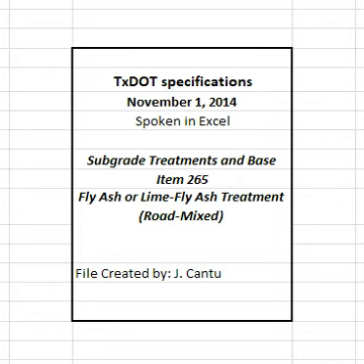4.7.2 FA treated sections with CS. Cure the finished section for at least 24 hours before opening to traffic unless otherwise directed. Curing may be accomplished by placing material to be used in the subsequent course instead of moist curing. Allow the treated course to dry for at least 48 hours before applying a prime coat.